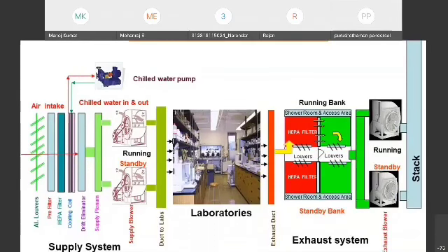And as a safety measure, this air will be treated as radioactive air. It's not radioactive, but since some radioactive experiments will be carried out here, there can be some chances of releases. It's not possible, but in our design, what is to be considered is that in case of an accidental condition also, the safety is to be ensured. That is the major design consideration which we take.